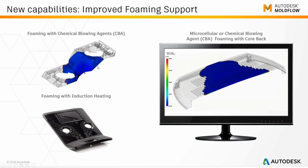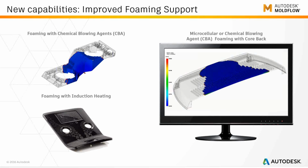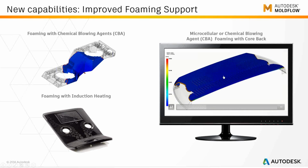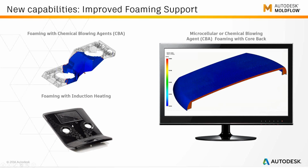We also added the ability to use chemical blowing agents, or CBAs, as they are commonly referred to. What you would have to specify is how much chemical blowing agent weight you added to your material, as well as how much of that chemical blowing agent solid material will actually be converted into a gas. Once it's in a gaseous state, it effectively follows the same process that you'd normally get with the MuCell process. We also added the ability to run induction heating analysis or rapid heating and cooling analysis in combination with the foaming technology, either chemical blowing agents or with coreback.